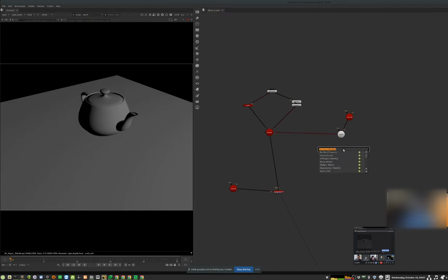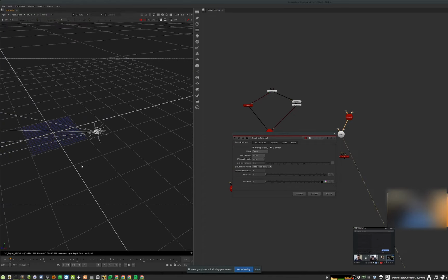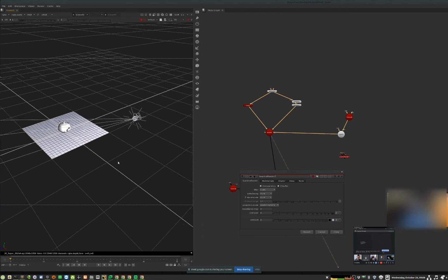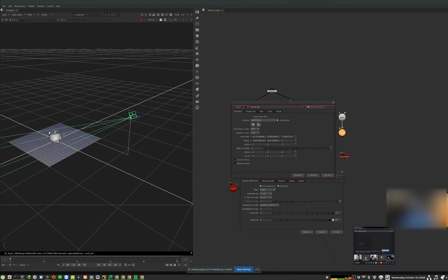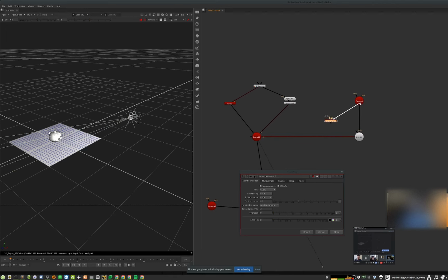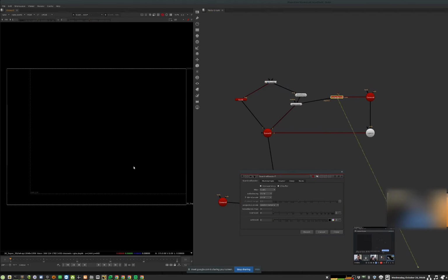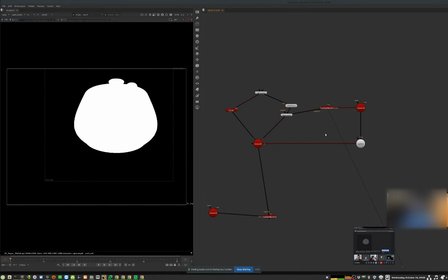So pretty straightforward. I'm going to bring another scanline render. I have the light over here. It's in the scene over here, so I can actually see it. Okay, that's what we're actually seeing. In this case, I already have the camera. It's supposed to be the other way around. Basically, I can put it like that, and the camera would be connected to the light. But because of the way I built it before, the camera is actually what's leading the light, but it doesn't really matter, as long as they're in the same place. I'm going to connect the camera over here, and I'm going to render this from this angle. So we have these kind of things. And I'm just going to open it a bit so we can see what we're doing. Okay. And all we have to do is just project it.